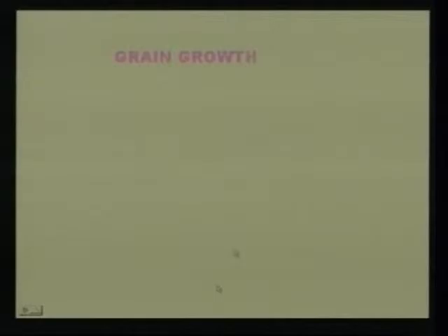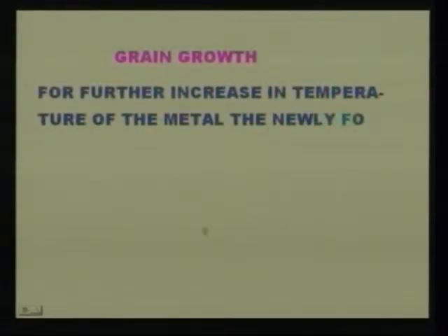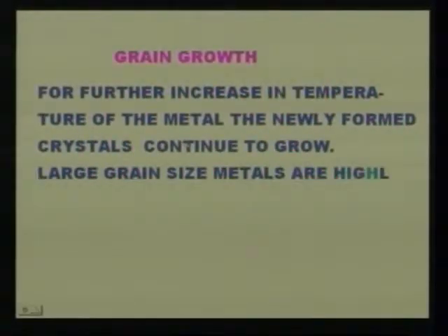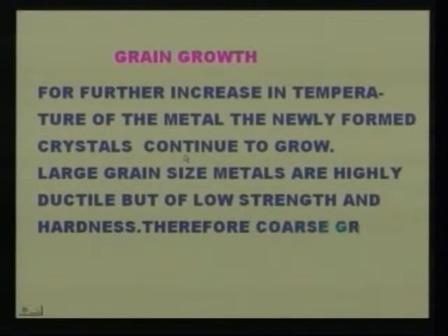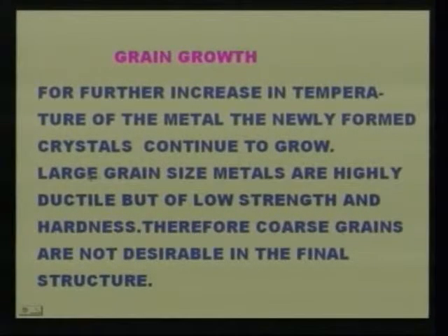Now, let us see grain growth. For further increase in the temperature of the metal, the newly formed crystals continue to grow. Large grain size metals are highly ductile but of low strength and hardness. Therefore, coarse grains are not desirable in the final structure.